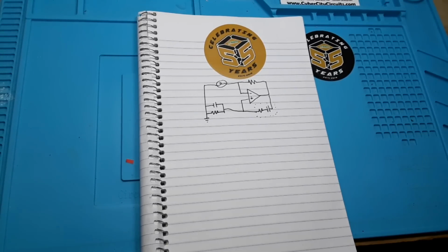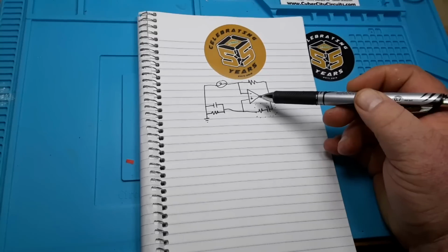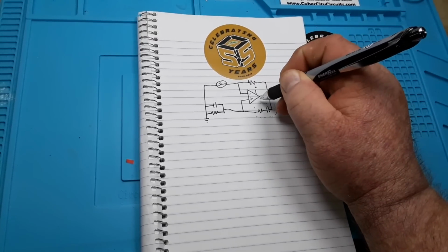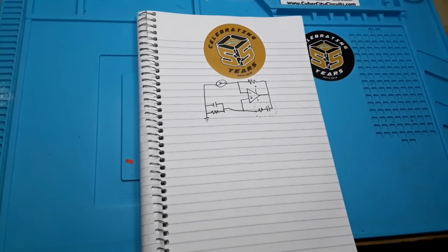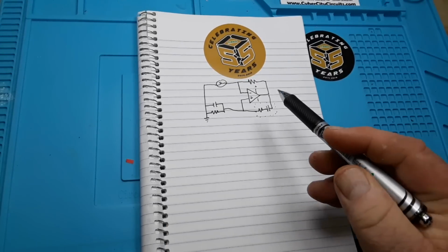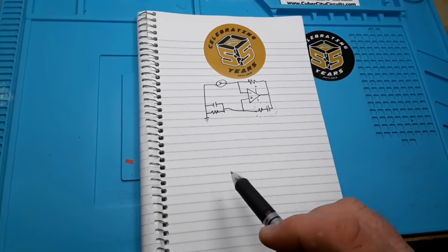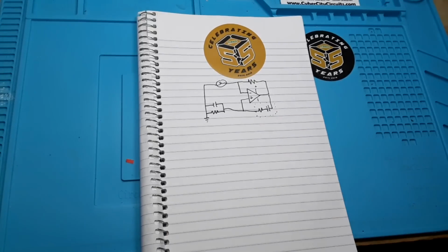It also has an automatic gain control in the form of an incandescent light bulb, which as it gets warmer, the voltage drops. So we have an op amp here, and you're going to have to imagine there's positive and negative connections. Then this is our gain control coming off of that little negative feedback loop, and our frequency is going to be controlled right down here.